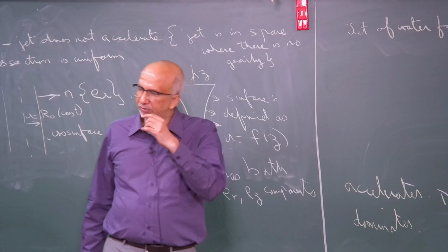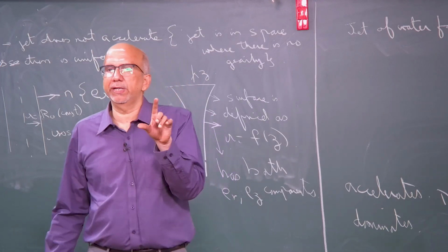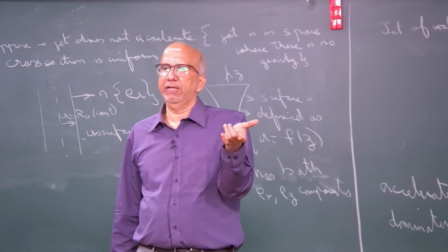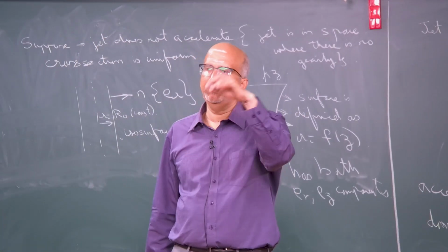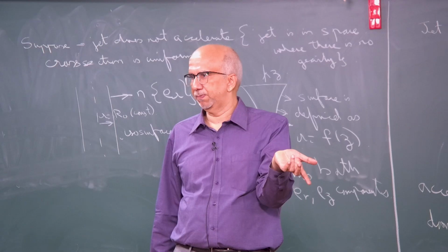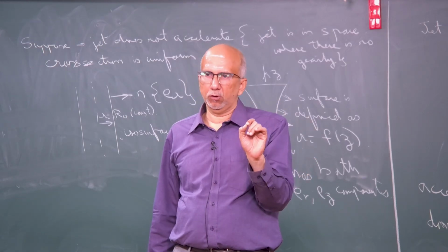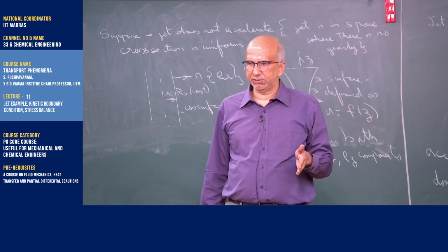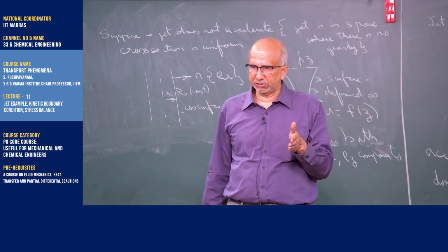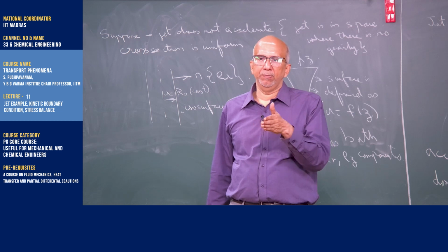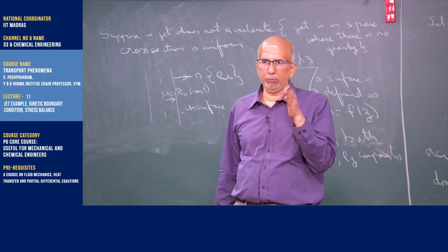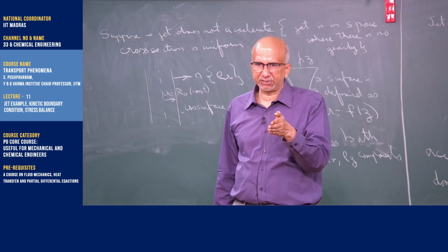We spoke about using n dot t to convert the surface integral to a volume integral, and then we got the differential equation. I am saying this n dot t concept is useful here also when I am going to apply boundary conditions. When I apply boundary conditions, I will say the tangential stress is 0, and I am going to put conditions on the normal stress.